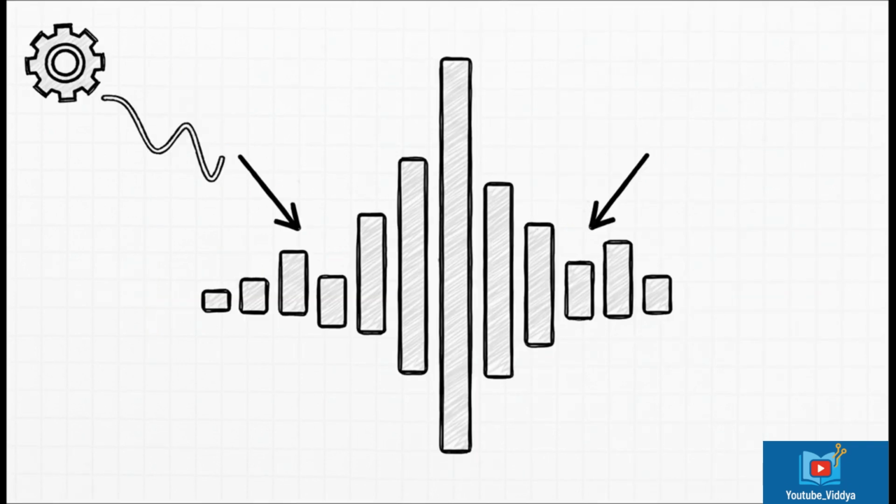Now, that was the time domain, but we can also look at signals in the frequency domain. This lets us do things like pinpoint the exact rotation speed of a shaft, or, and this is a big one, we can look at these things called sidebands around a main frequency peak. If you see those, that's a classic sign of a problem in a gearbox.